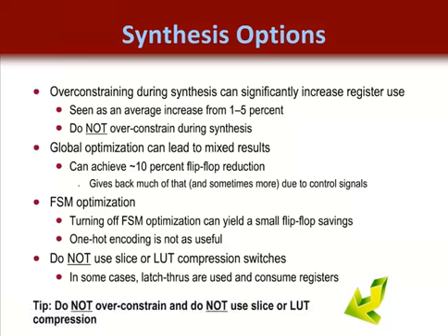So we don't recommend over-constraining your design. It just increases the register usage too much. We also don't recommend using slice or LUT compression switches. It can waste register resources.